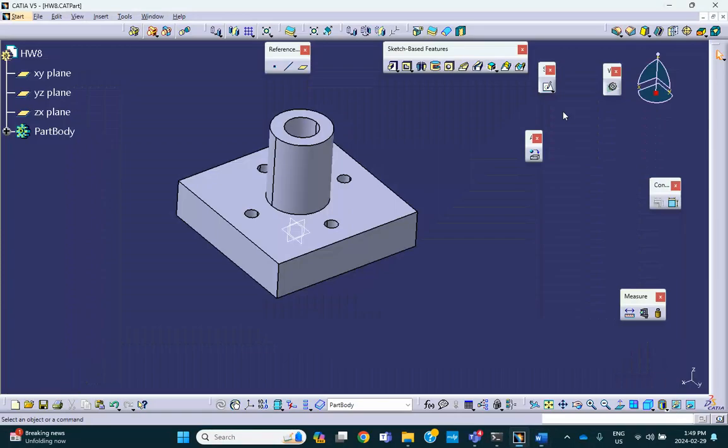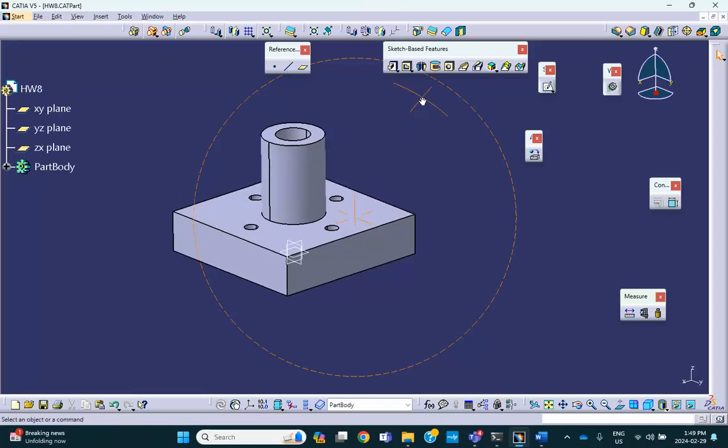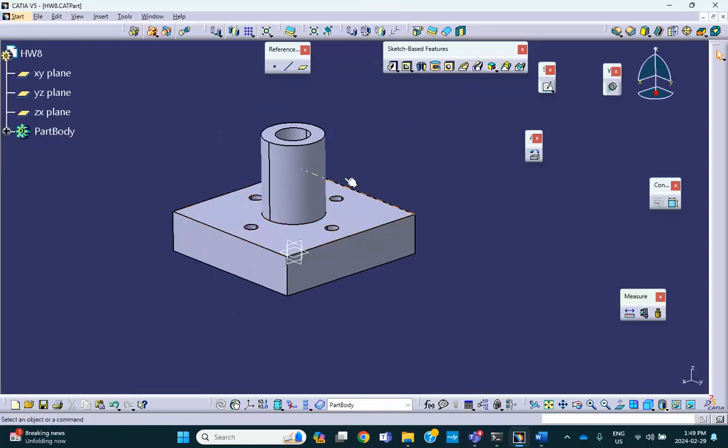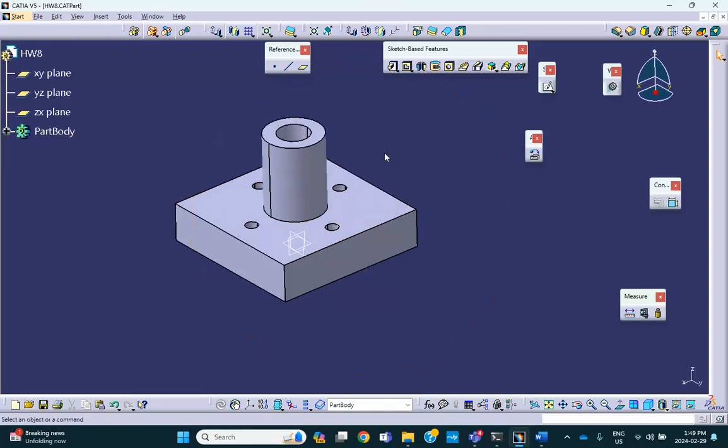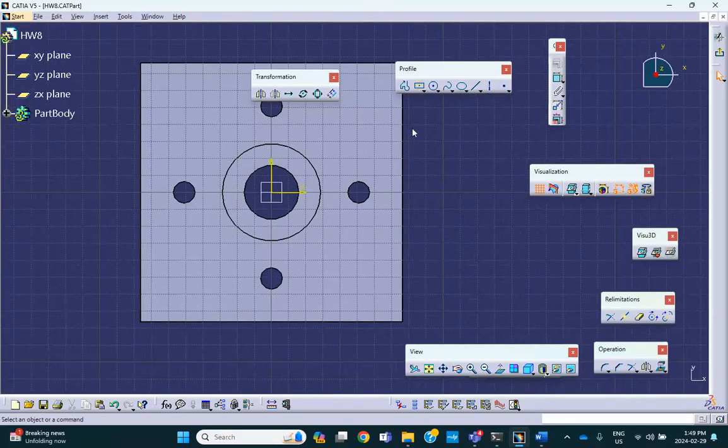Okay. Now I know it's crazy, but I'm going to start cutting it so we get 1/8 of the model. The question is, what is the easiest way of doing that? There are many ways, but here's the easiest way perhaps. On that face, I will sketch maybe a line like this, going from here to here, 45-degree angle basically later on.